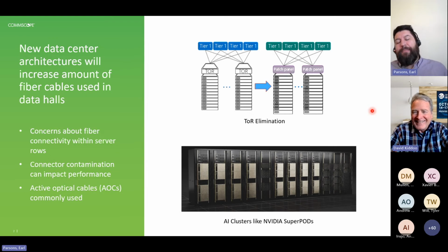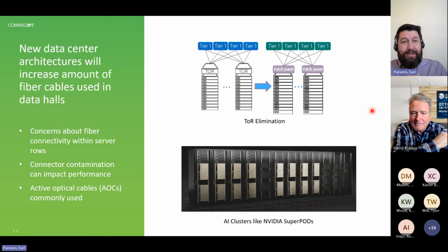Yes. So these are graded index, OM4 or OM5 typically. And it is a short reach, but we have to remember that we're looking at very high speeds here. 50 gigabit per second per fiber, 100 gigabit per second per fiber. Next, we're trying to define 200 gigabit per second per fiber. Even for the short reach, to be able to handle that high data rate, you need a good bandwidth from the fiber. And you get that from graded index, you get that from your OM4, your OM5.